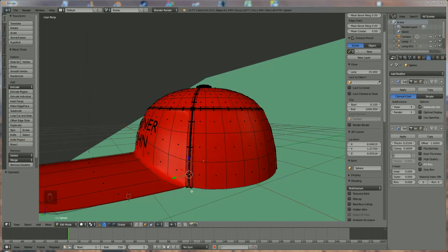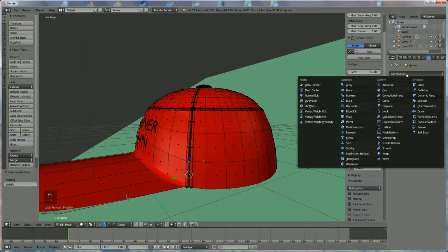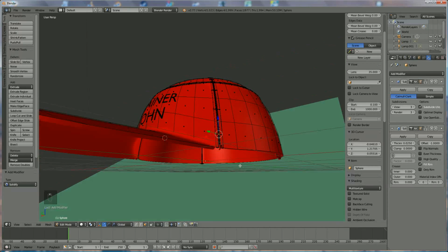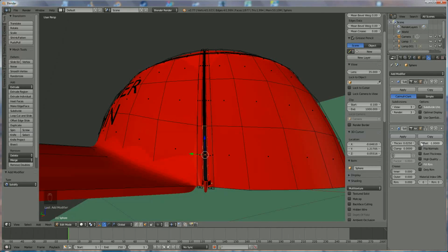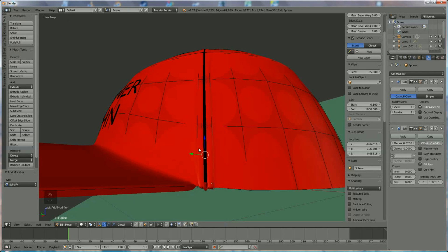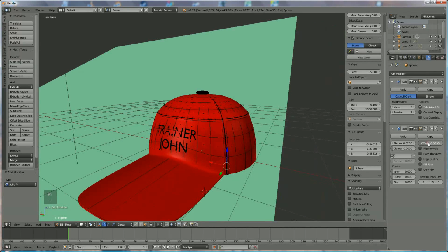For those guys who are getting in trouble over here, it is because you have to switch off the solidify like that, add it again when everything is done, and now add the thickness, and then your problem will be gone. It took me a while to find it. I had forgotten it when I made it again. You see that it pops up, you see? And now if you switch here, let's say to something like 0.7 or 1, like that, it should be gone. But it depends a little on what you have, so you have to pay attention to that.